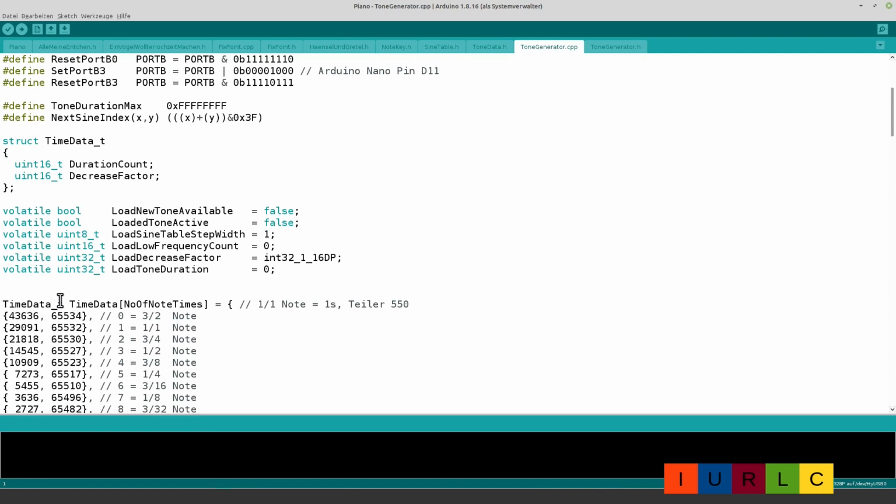Here are the transfer variables to transfer the data from the main program to the interrupt service routine, and the flags to ensure complete data transfer. All variables are marked as volatile. This is so that the compiler makes no pre-assumption of the contents of these variables due to preceding calculation steps. The variables can change their value all the time because there are two parallel processes which have access to these variables, the main program and the interrupt service routine.